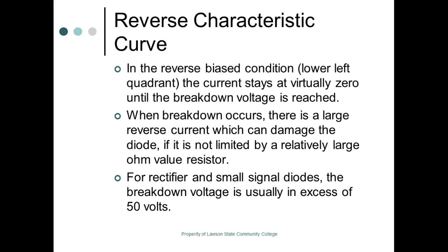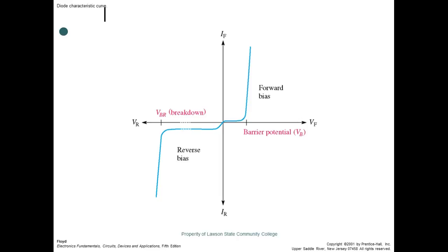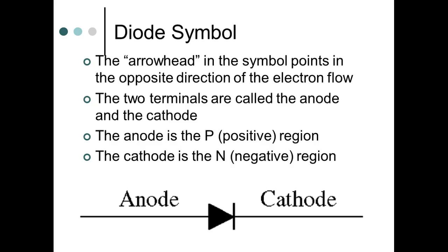So this is forward bias. That's reverse bias. We've already looked at the symbol. Everybody okay here? Okay, this is the symbol for a diode. It's supposed to be colored in, but you're going to see me up here a lot. I don't color it in. A lot of people don't because it just takes time. The arrowhead itself is representing the P material. And then the bar right here represents the N. And that's basically what tells you what you have to do to forward bias.